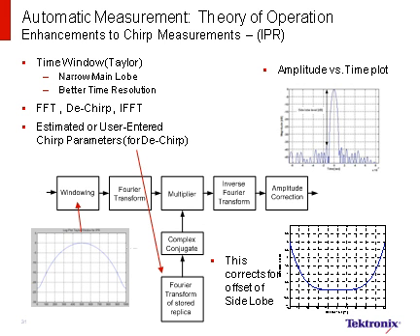After the RF pulse is digitized, a time window is applied to reduce the unwanted side lobes. The resultant FFT mathematics assume the input signal is not limited in time. For IPR, a Taylor window is used for good comparison between the main lobe and residual side lobe levels. After the windowing, an FFT or other discrete Fourier transform is performed, giving the frequency domain intermediate result. This spectrum is multiplied by the complex conjugate of an ideal chirp that de-chirps the pulse. The ideal chirp can be estimated by a measurement routine that is the best fit against the incoming signal, or the user can enter the details of an ideal chirp slope for more accurate measurements.